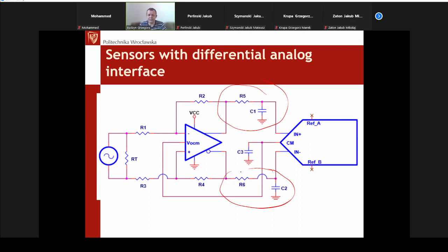Of course, their basic functionality is to protect against aliasing the signal back into our baseband. But we can also improve the filters, make them lower noise, and narrow their bandwidth to reduce the noise incoming into the ADC.